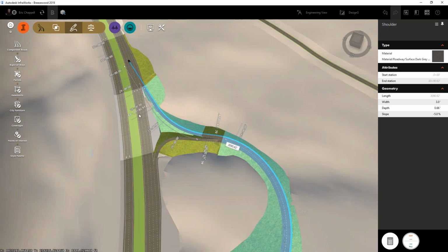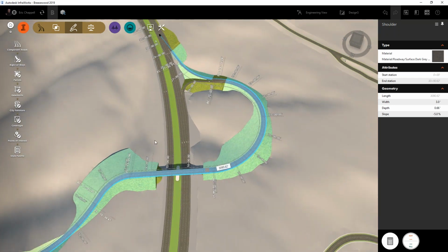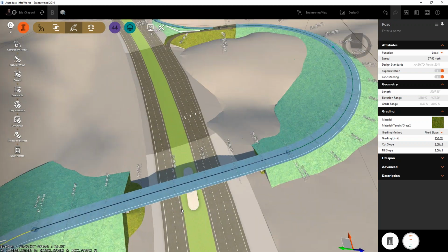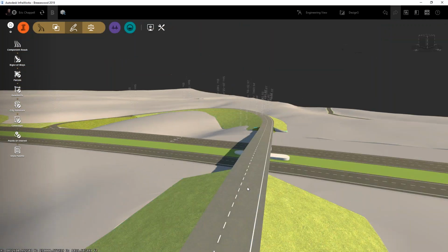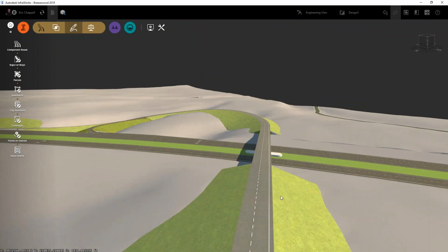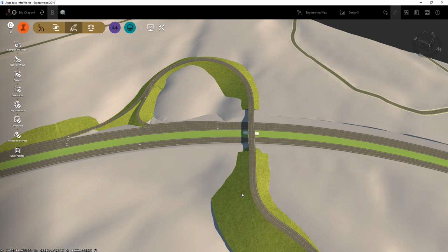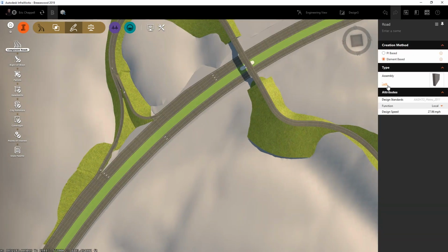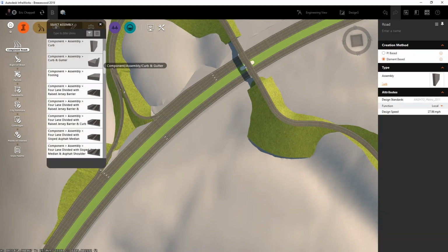Okay. Thanks, Elliot. Okay. So by making that stripe and shoulder go the whole way to the beginning, I'm on my way to defining the two-lane portion of the overpass as well. Okay. So let me put my last two ramps in. Those are pretty quick and simple. And this time, I'm going to actually use the assembly that I created. I think it was called Ramp X.